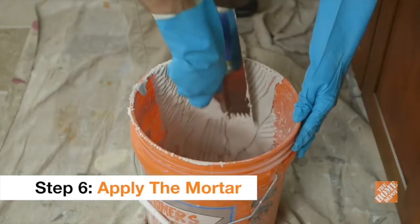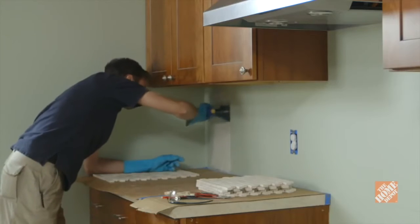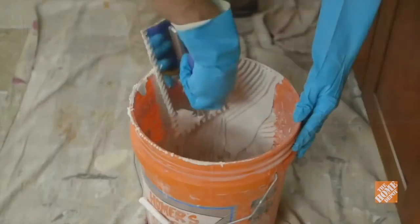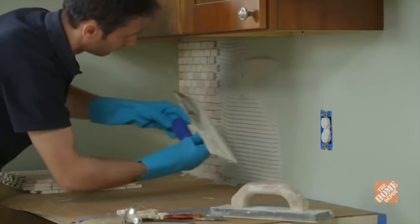Next, begin with a 2-foot section and apply the mortar to the wall, spreading a thin, skim coat layer of the mortar with the flat side of the trowel. Press at a 45-degree angle. This will ensure that the mortar fully adheres to the wall. Then, using the notched edge, add a little more mortar onto the trowel and comb even ridges in one direction.